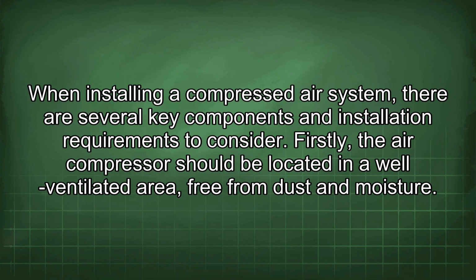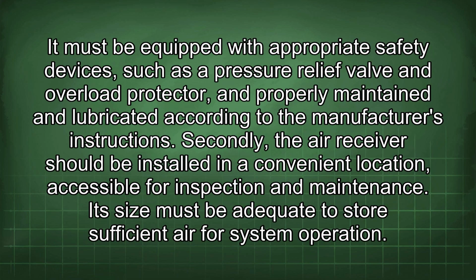When installing a compressed air system, there are several key components and installation requirements to consider. Firstly, the air compressor should be located in a well-ventilated area, free from dust and moisture. It must be equipped with appropriate safety devices such as a pressure relief valve and overload protector, and properly maintained and lubricated according to the manufacturer's instructions.